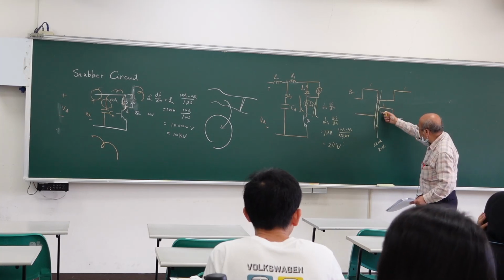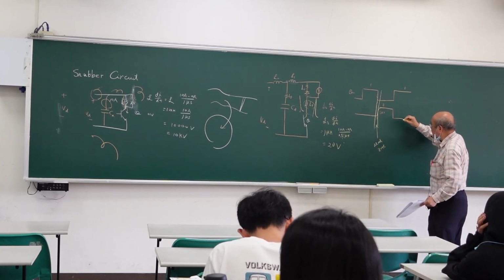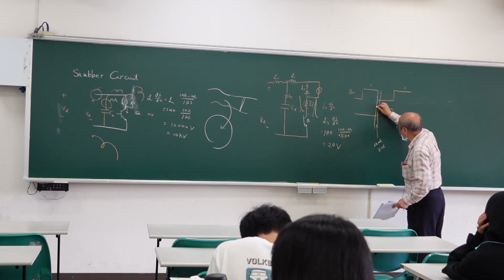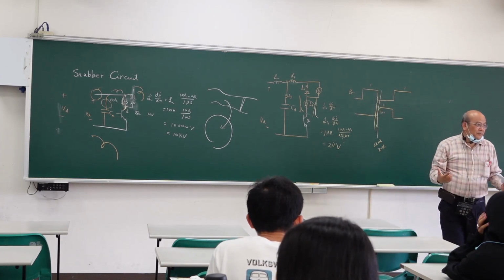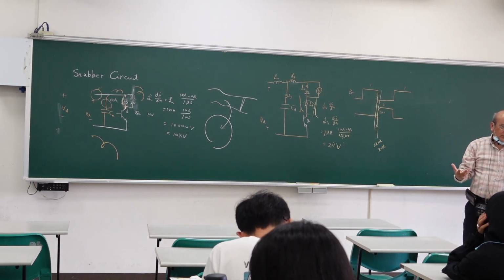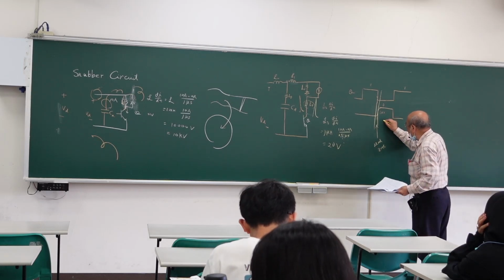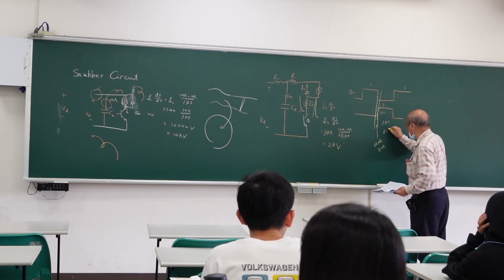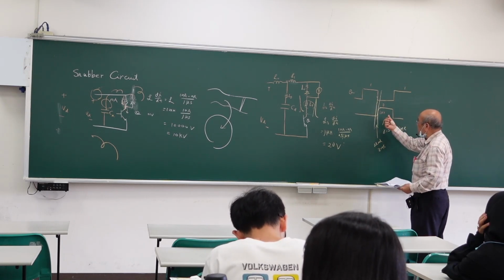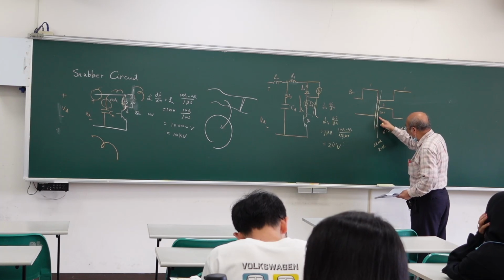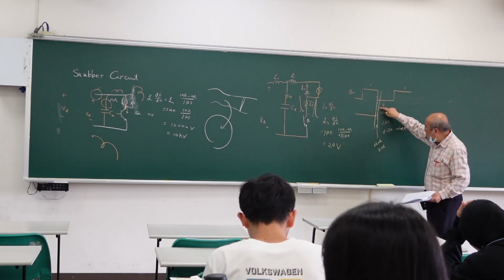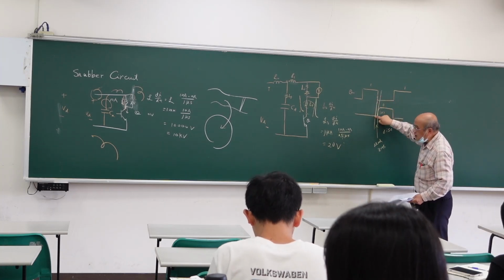It is impossible to connect this perfectly. Q turns off, D immediately turns on. Impossible. Because the diode has rise time, right? Every device has rise time. The rise time is only 1 microsecond. This is called rise time. So although the diode tries to trigger, tries to turn on, after 1 microsecond it becomes fully turned on. But before it turns on, Q already turned off.